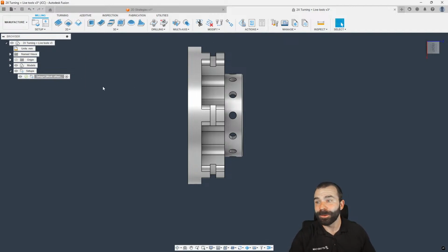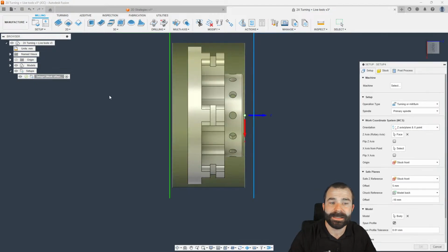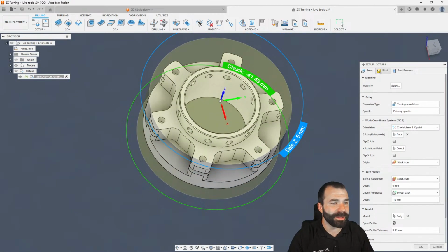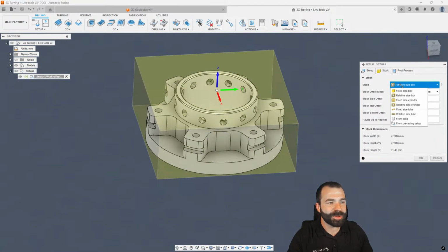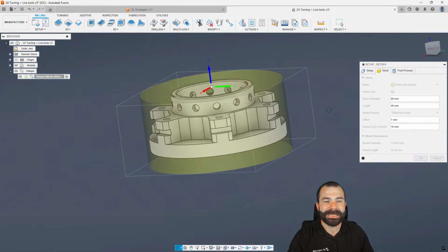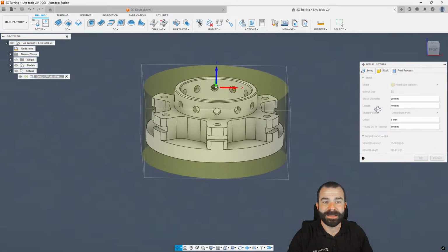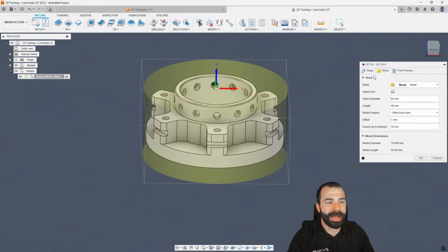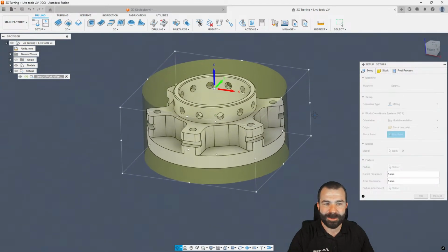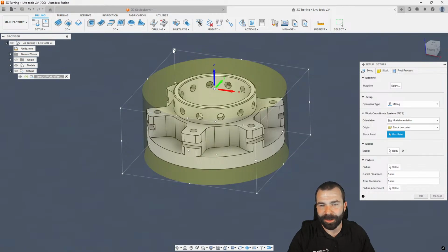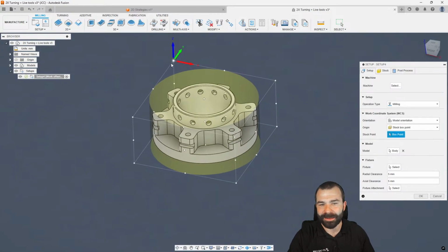Now let's pivot back real quick. So Deep Thinker, as you're asking here, if I was doing this based on a setup for milling, and then my stock was round, what you notice is it's identical to what I've done so far, right? So now, as I set this part up, I can still base things on a stock box point. Now, it might be a little unrealistic to use like a back left corner. Again, that's the outermost corner on those 2 edges. But I could also go in and I could put this on center.